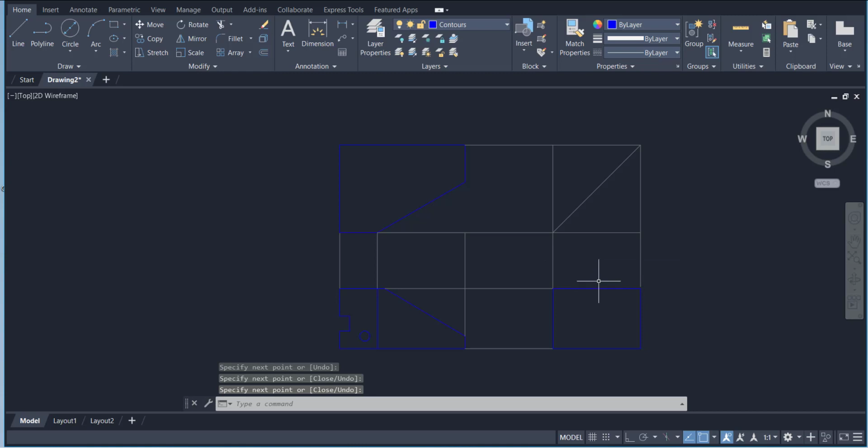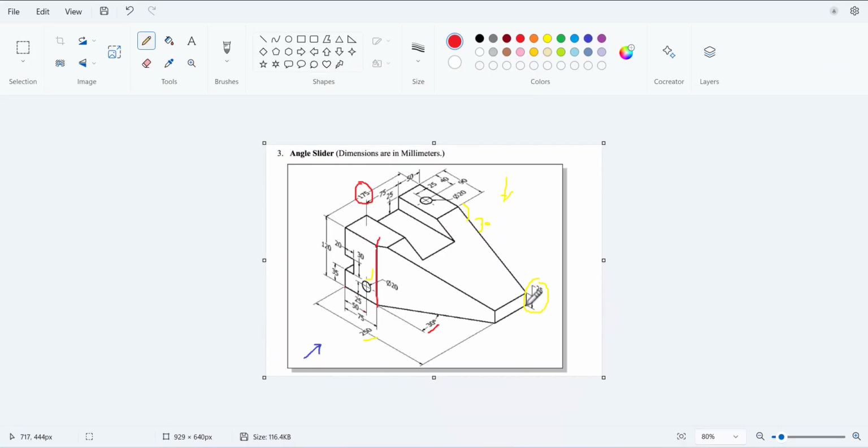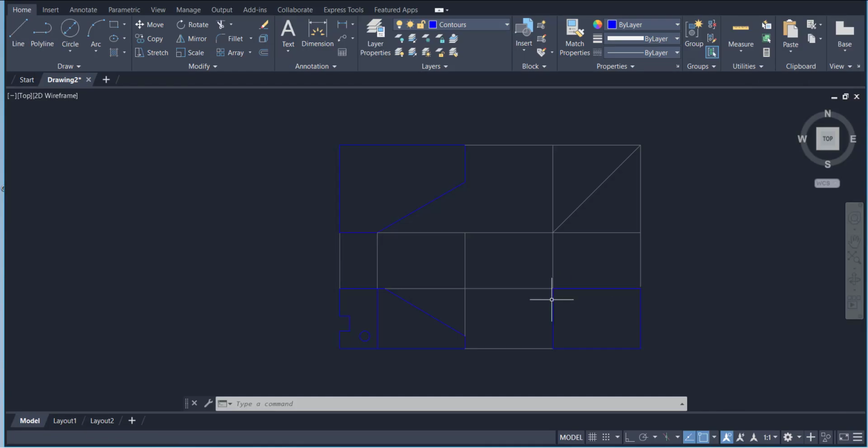So this box is for the side view. If we see it from this side, like from here to here like that, this side we will see. So we just draw this right side here. This is the right side, and we track it. Okay, now draw a construction line for this point.